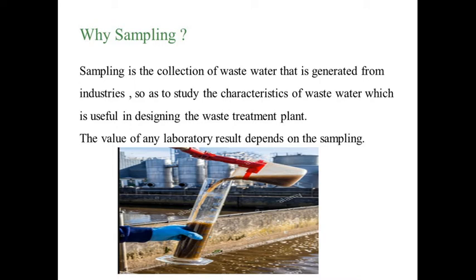The sample should be taken in a clean, colorless glass bottle provided with a glass top. This one thing is very important. So the sample should be collected in a clean, colorless glass bottle, and mostly we prefer the BOD bottle for the collection of the sample.